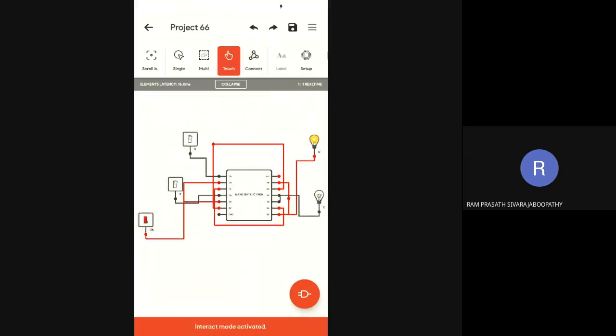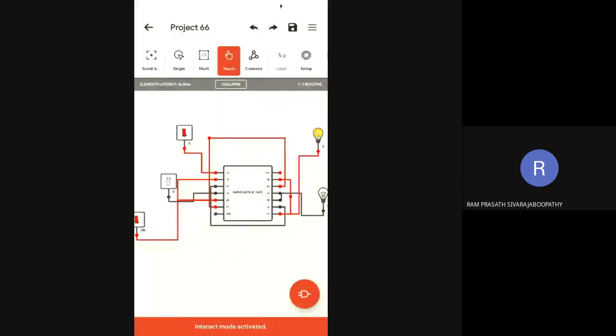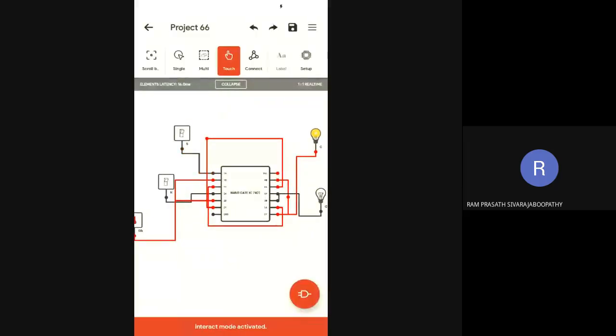So I keep the clock at enable. Set. When I set, what do I get? Q equal to 1, Q bar equal to 0. Then in memory state, it is maintained. Now I reset. So Q equals 0 and Q bar equals 1. Again in memory state, it is maintained: the present state is maintained as the next state. That's all. Is it clear for everyone?